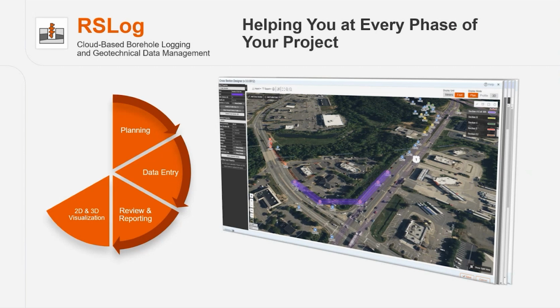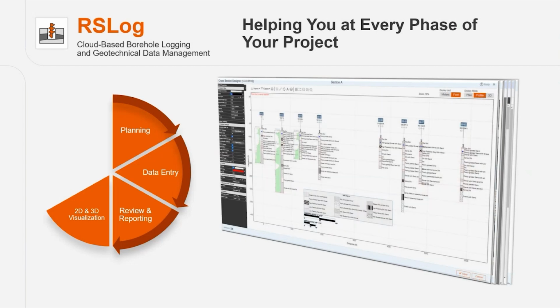And what we do, we automatically project those boreholes onto the center line of the cross-section. We calculate the offset, we calculate the distance from the beginning of the cross-section. And then what you do in the next phase, you switch to the profile view, and we show you the stick logs of all boreholes that participate in this cross-section. And as you see in this example, all the groundwater levels and different soil layers, even SVT data is shown. You can select one lab test or field test to show on the left, and another one on the right side of the borehole.